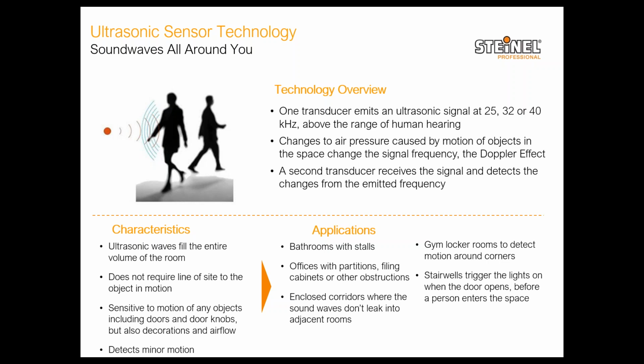In case of corridors, one thing I missed about PIR technology is that you get the best detection from a PIR sensor when you're moving tangential or perpendicular to the sensor. So imagine a circle of coverage around the sensor, and then if you start moving along the perimeter of this disc with the sensor at the center, then that would be your best detection. That would give you the biggest coverage pattern.